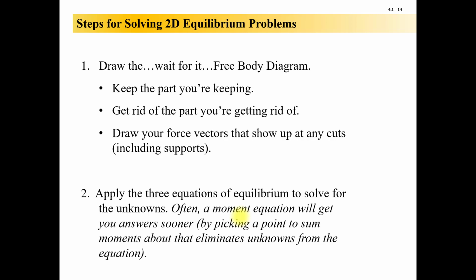Don't be the schmuck that sums moments about point A, because the one value you're not going to get is point A's value. You'll end up getting point B's value, and then you'll be like, oh wait, now I can sum forces in X or Y and get A. That's true, you can. It's just going to take longer. Moment equations are great. Think of them first.